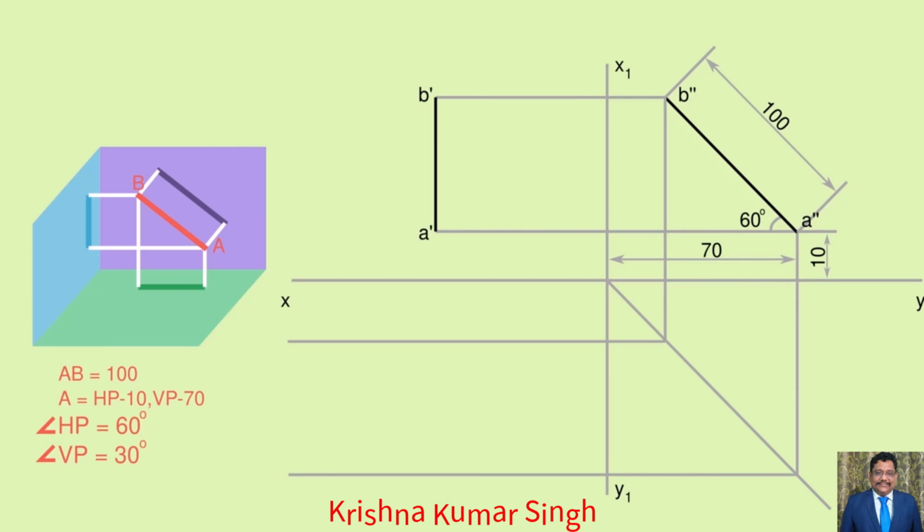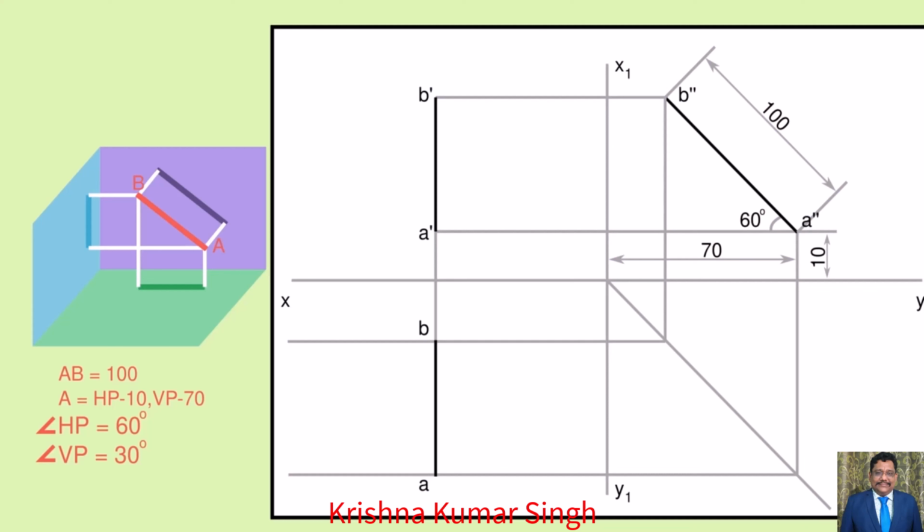From there, draw horizontal construction lines individually on HP. Extend the construction line down from the front view. These two lines intersect each other and identify the similar points. Name it as AB. This is our required top view. Keep the dimensions as much as we need for our views. Hence, our orthographic views can be made by the following procedure.